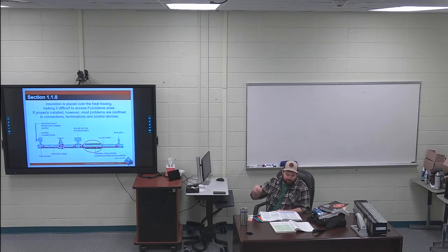Electrical heat tracing application, right-hand side of page 2, first full paragraph, first sentence, the one with viscosity is highlighted. Broad temperature control, so wide range control, is used to maintain the viscosity of process fluids in order to keep them flowing. So it's not worried about if it turns into a slurry or anything like that. It's just to keep things from freezing all the way up.